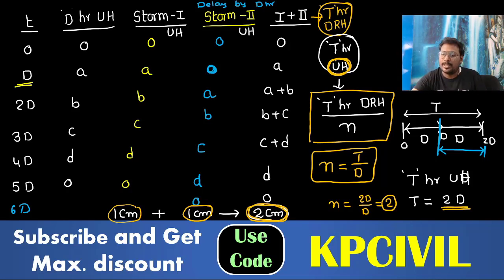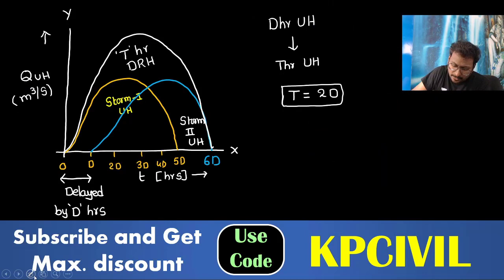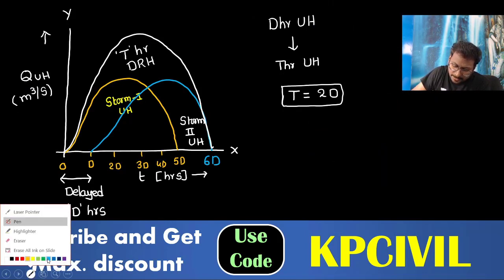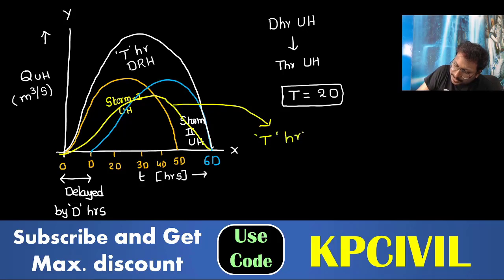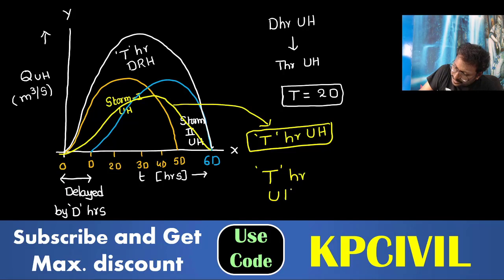So you will get UH values. If I plot the UH value, where does it come? It is less than the UH values of D hour. So this yellow color that I am plotting is the T hour UH. Very important: T hour unit hydrograph discharge values are always less than D hour unit hydrograph discharge values.